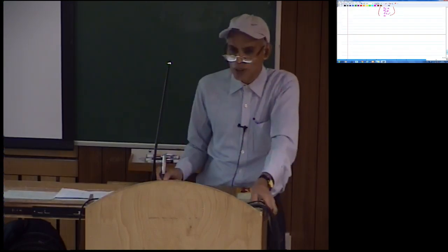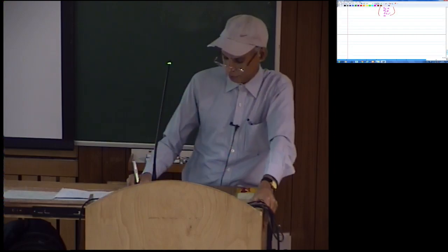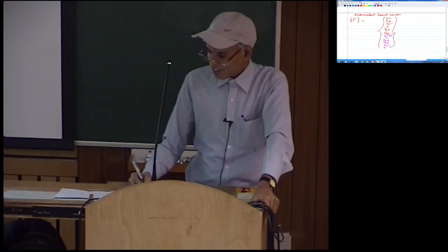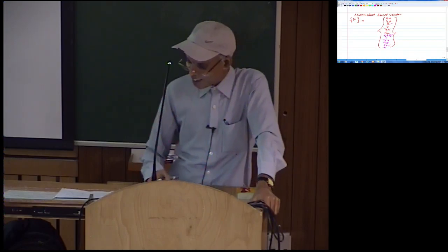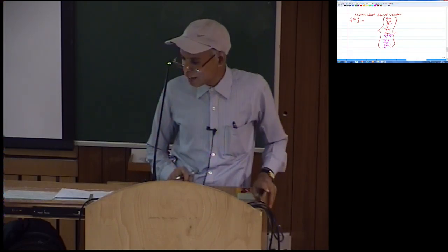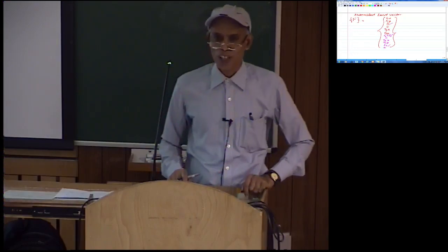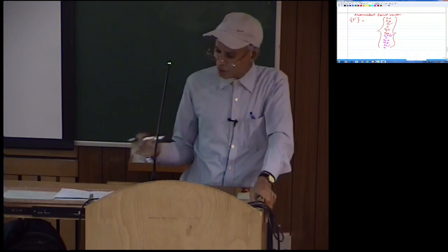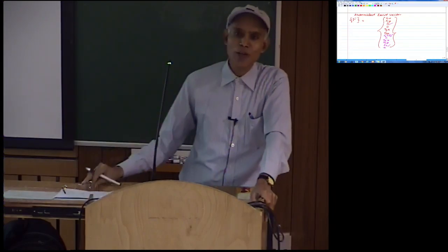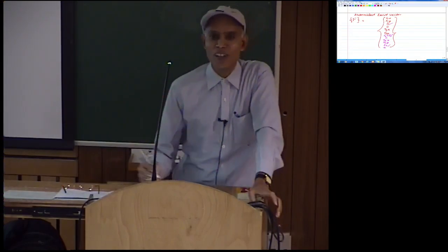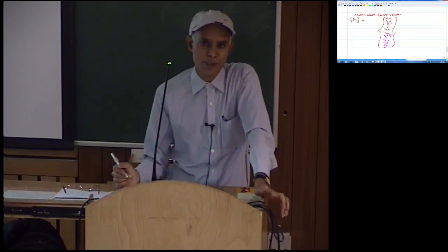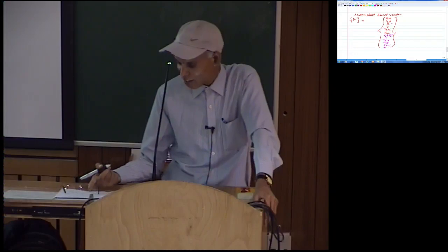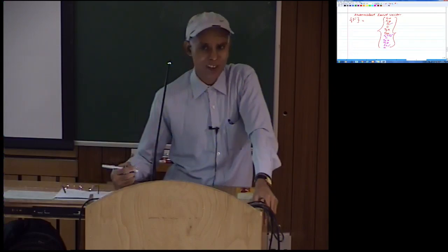So this is what I expected you to do. Since I had mentioned a 4-noded isoparametric element, I expect you to do that. Of course, you can also do the formulation, if that was not there, then you could have calculated the load vector using formulation in physical coordinate space, using shape function in terms of x and y. So that was possible, but here I had said a 4-noded isoparametric element.